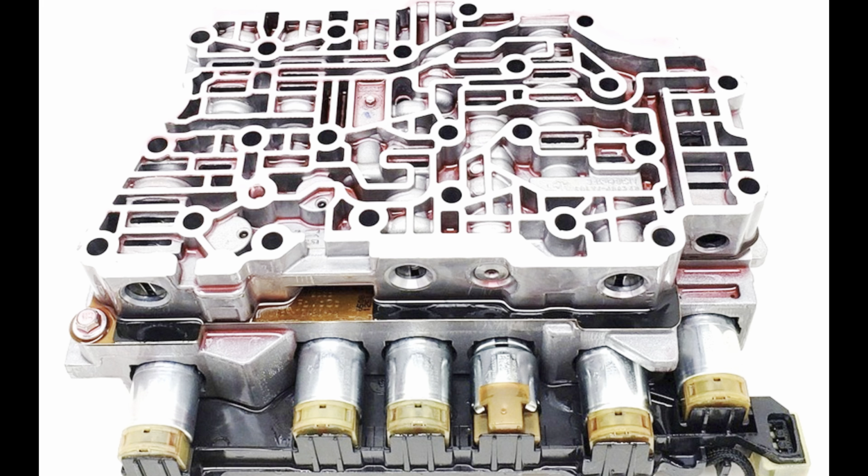The most important valve, and the one that you have direct control over, is the manual valve. The manual valve is directly connected to the gear shift handle and covers and uncovers various passages, depending on what position the gear shift is placed in. When you place the gear shift in drive, for instance, the manual valve directs fluid to the clutch packs that activate first gear. It also sets up to monitor vehicle speed and throttle position, so that it can determine the optimal time and the force for the 1 to 2 shift. On computer-controlled transmissions, you will also have electrical solenoids that are mounted in the valve body to direct fluid to the appropriate clutch packs or bands under computer control to more precisely control shift points.